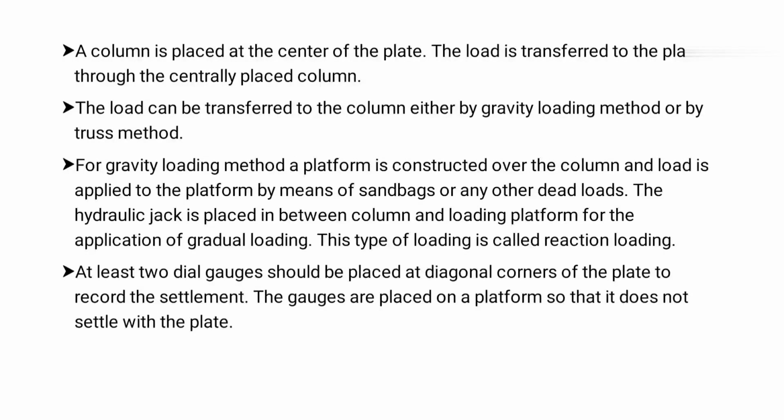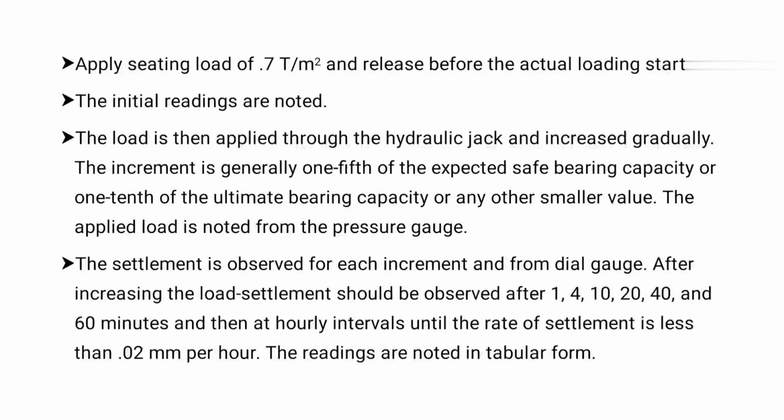Next, two dial gauges are attached diagonally at the corners of the plate to record the settlement of the plate due to the application of load. First we apply a seating load of about 0.7 kN per square meter and release it before the actual loading starts. Next, the initial readings are noted, and load is then applied through the hydraulic jack. The increment is generally 1/5 of the expected safe bearing capacity or 1/10 of the ultimate bearing capacity.